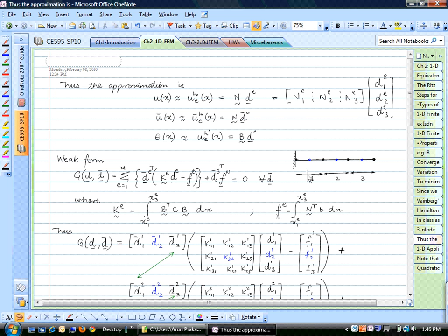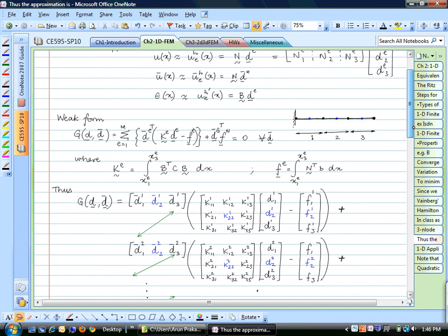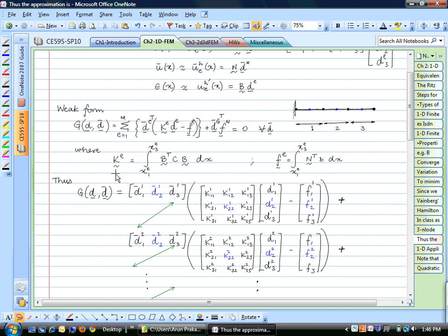So here again, I'm just showing you that the boundary value problem that we are trying to solve could have m total elements. In this case, I've just shown 3 elements. And I've labeled the middle nodes with a blue color just to demarcate them, and I'll tell you why this is important. So then this is the stiffness matrix for the element. This is the exact same formula that we had before.